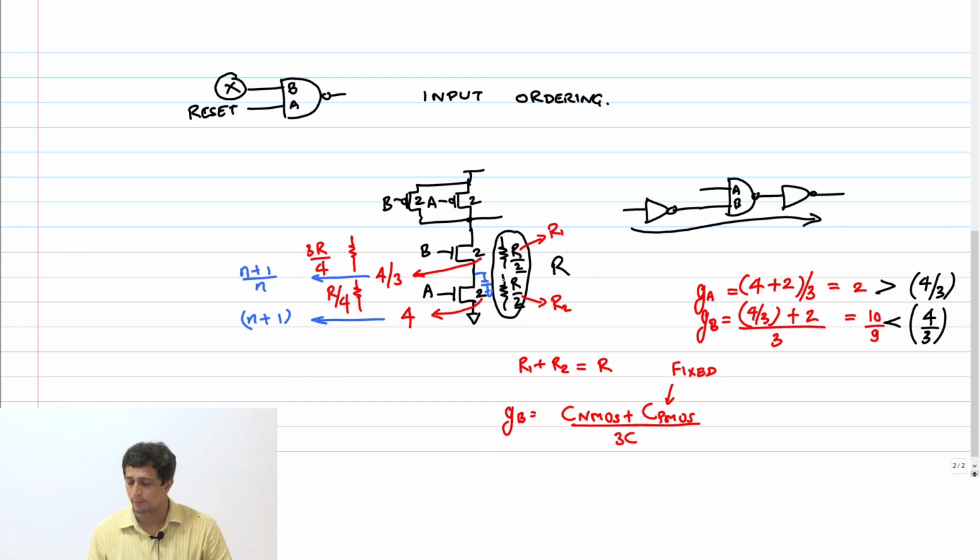So what happens to the parasitic delay? So again, yes, that will change. You've got to recalculate all that a little bit. And in fact, even here, you're right that you have to look at the layout now. However, it is still true that parasitic delay does not change if I upsize this gate. That still remains true. Therefore, my gate sizing algorithm still doesn't care about it. It's a constant number. You have to calculate a new number. It's a constant number. Forget about it.